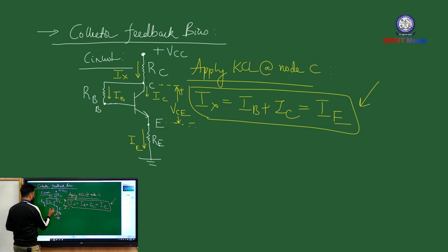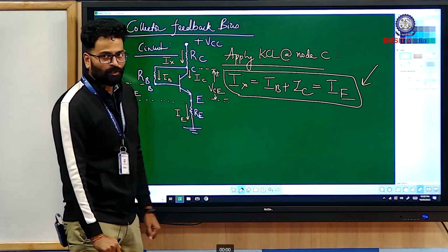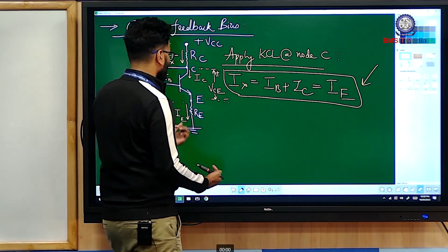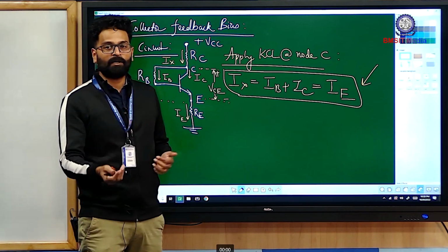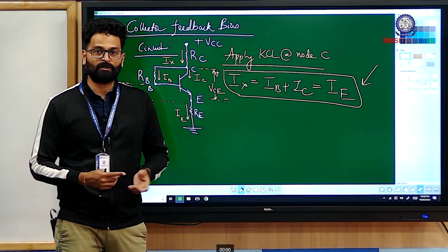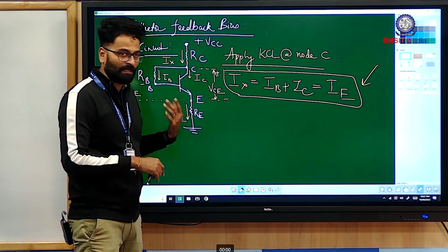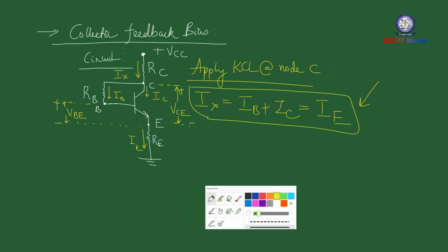On the other hand, on the input side, you have terminal voltage VB, again upper side positive, lower side negative. Okay, once you mark the terminal voltage, you can identify the loops. You don't have to create an equivalent circuit in order to apply KVL. Being at this circuit, you will be able to apply KVL in a simple manner.